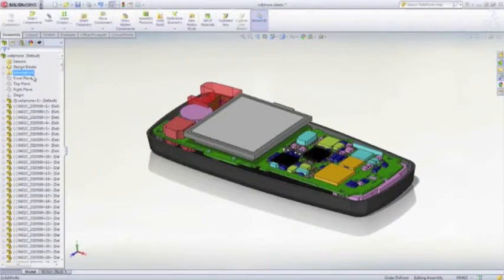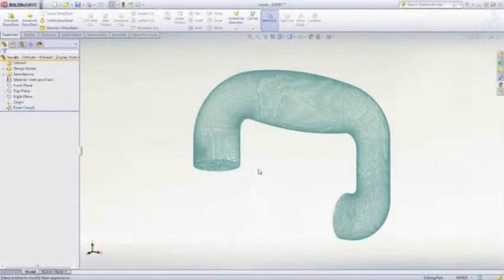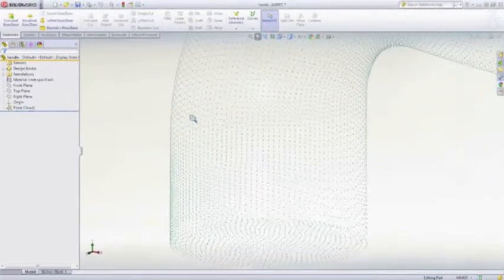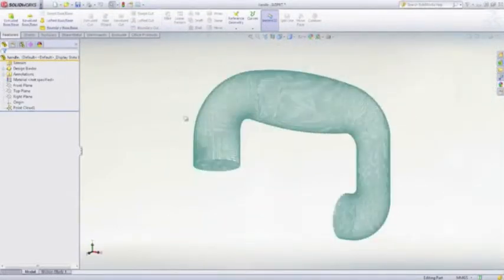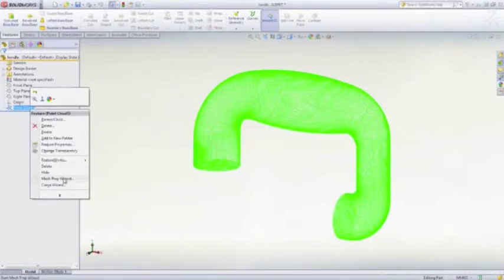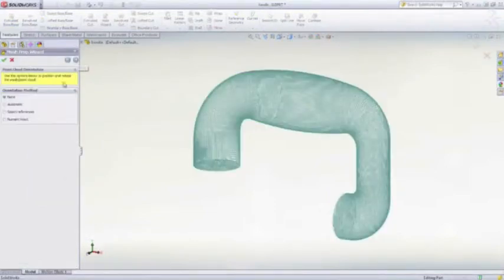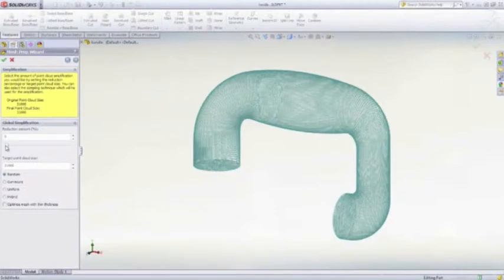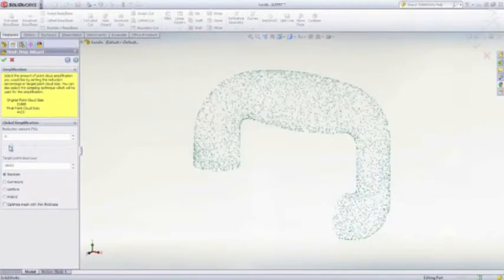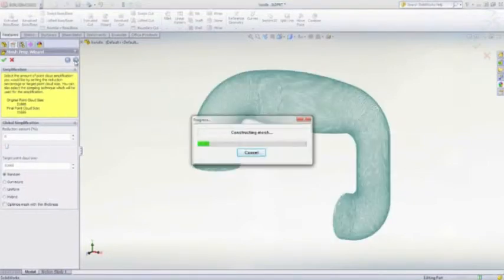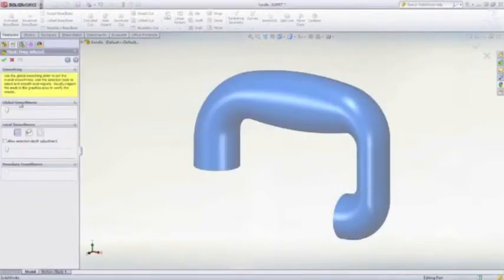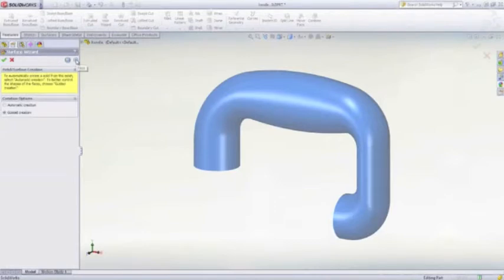When ready, the board can be built as a 3D assembly model from the customizable component library and ready for use in your designs. The Scan to 3D feature allows you to import scan data, mesh and point cloud files into SolidWorks and then convert it to a 3D surface or solid model. It uses a guided wizard to position the point cloud and remove noise or extraneous data such as fixtures that were used during the scan process. The simplification feature can be used to reduce the number of vertices to yield a more efficient mesh. And finally, the model can be smoothed to help rectify jagged or unrefined areas.